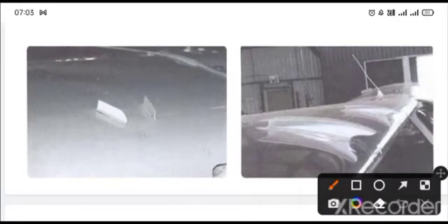You can see these are the sections, these are the aluminium strips. Over here also you can see in this picture. What do they do? They energize the boundary layer so that it doesn't stop. Whenever the boundary layer comes like this over the wing surface, they allow the air to pass through them and it becomes more energized.